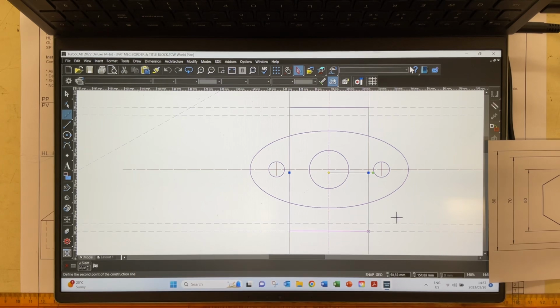Now, once I go in there, I'm going to click on that. Remember, I'm still setting my angular construction line, and you can see that it's still swinging around. If I press Shift, it automatically goes to that 30 degrees. There it is. Press Escape. Go to this line up here, get it more or less in that orientation, press Shift, and that gives you 30 degrees there.